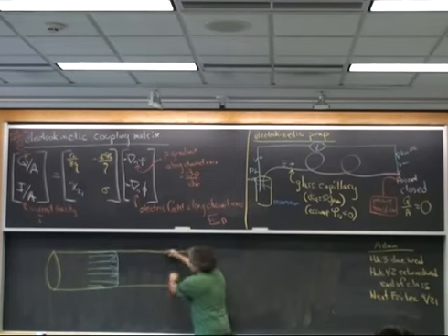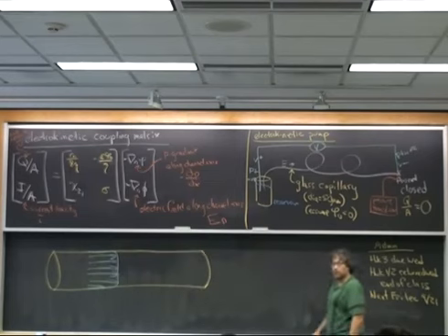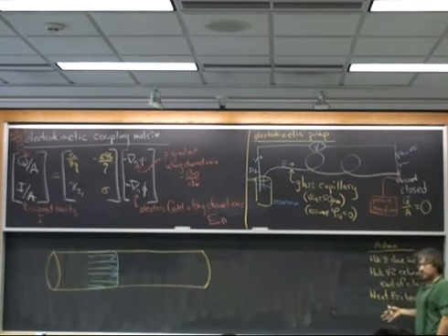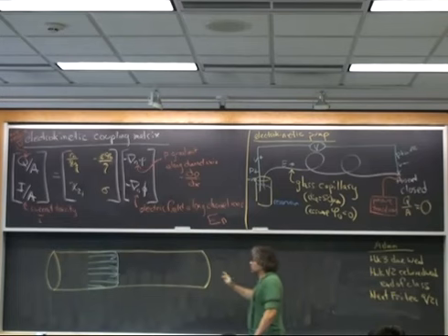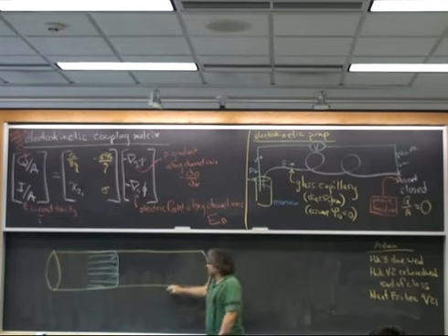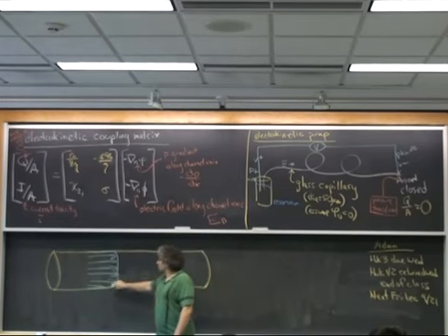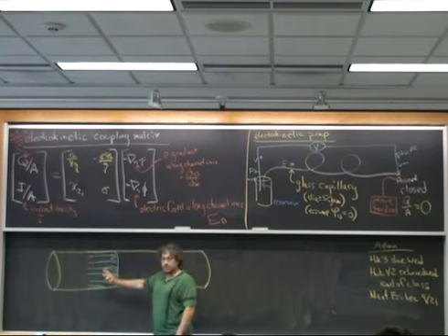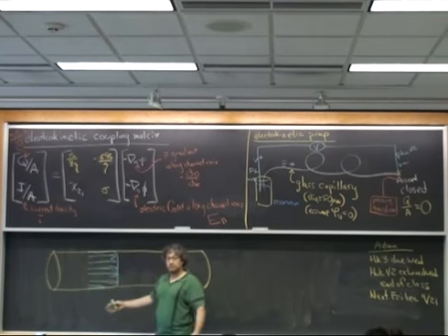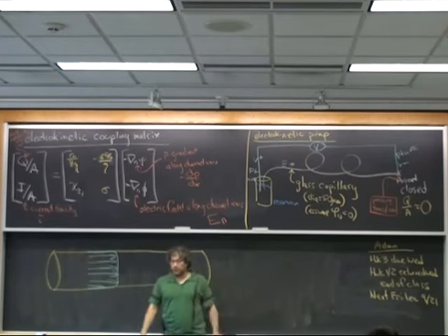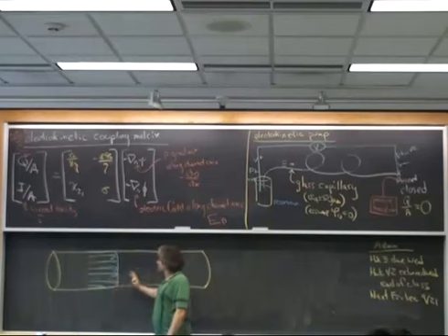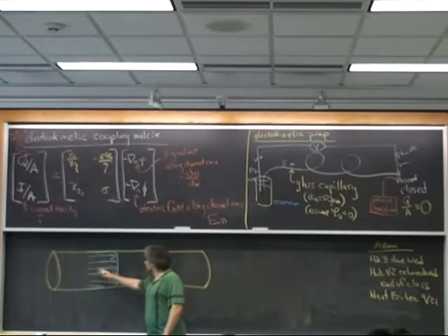If I have a bubble that I'm compressing, if this capillary is stretching out a little bit because of the increased pressure, pretty quickly this system goes to equilibrium. Well, how can the system go to equilibrium, or more precisely, steady state? Somehow, the net mass flux that I see in this flow has to go to 0. So it can go to 0 if the electric field goes away, except it doesn't, because I'm controlling the electric field with my power supply. So what has to happen? Well, there has to be a counteracting pressure-driven flow.